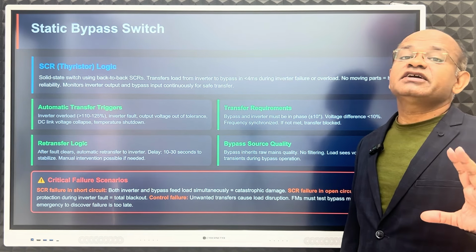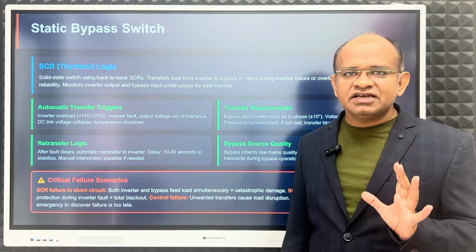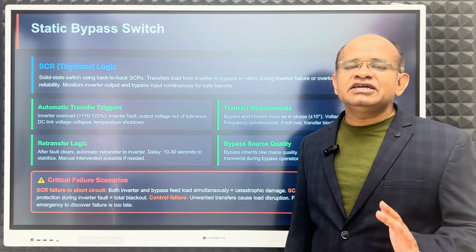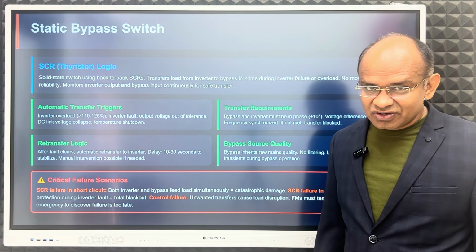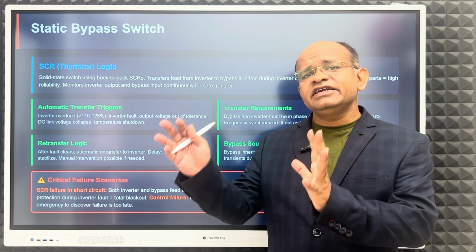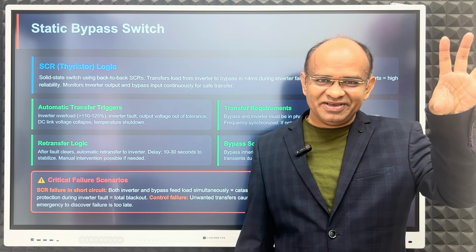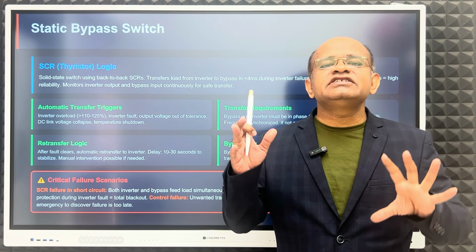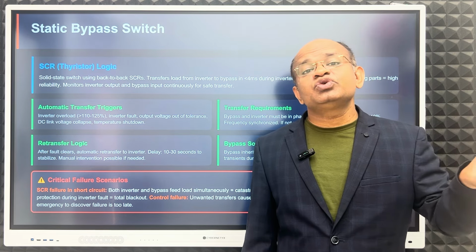That is why N plus 1 or N plus 2 redundancy is required in case of critical loads, so that all the time the load will be catered through the UPS only, not through raw mains. In many cases I have seen, the critical UPS bypass is connected to a lighting UPS, so that even the lighting UPS or another standby UPS should take the load.